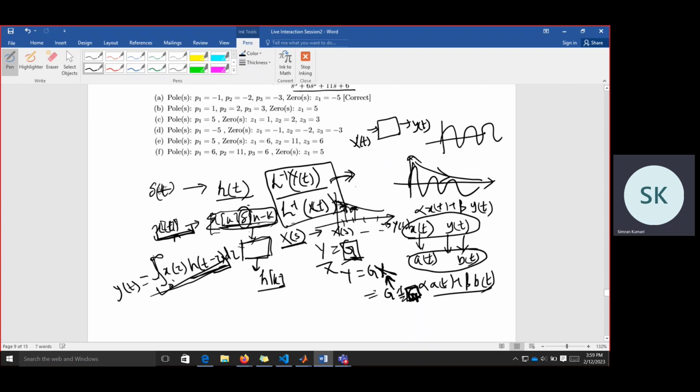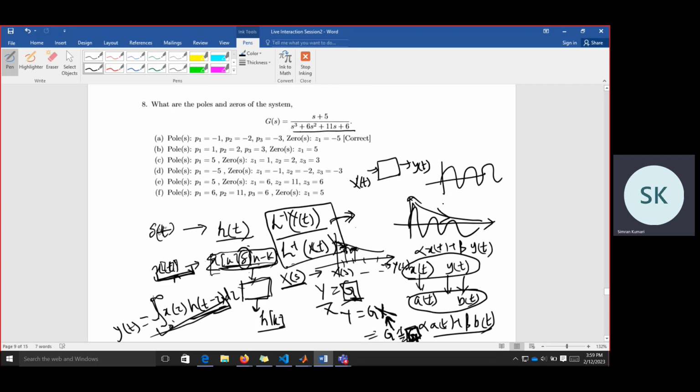Also, from the Laplace transfer function, you can see, if there is no input and there is some initial condition of the system, how the system will behave. That will depend on the roots of this, that means the poles of the transfer function. If the poles are negative, it's like what you had seen: e to the power minus t is a signal.